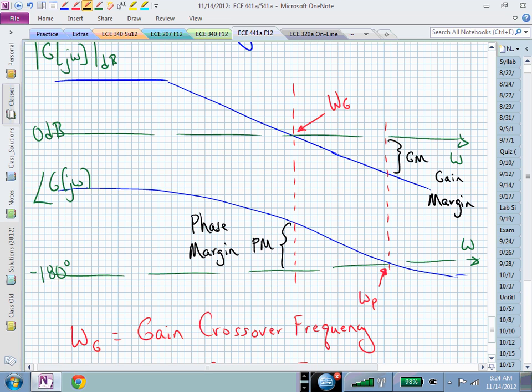Pardon? The air. Now the air might be... I've talked mostly about the air. Now I guess that's true, you maybe won't be able to track as accurately as many frequencies as what you could before. But if you look at how this is related to the closed loop, this will actually influence your speed of response. That omega sub g being further to the right will give you a faster behaving system.